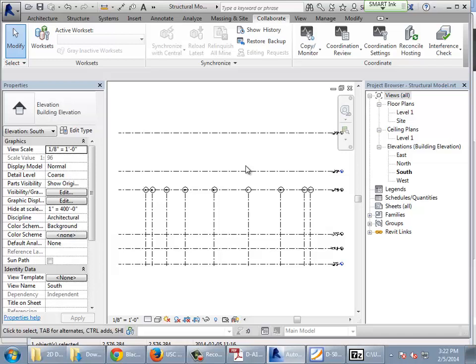But again, hopefully this won't happen to you too often. Strange, I wonder what you guys have done. Well, I saw the new level, so I just deleted the old one and matched. Ah, okay. So although it's matching, it's not really linked. If you copy monitored, it would work. I did copy monitor and I got that message, but I just didn't know what to do. I didn't know to go to coordination. No worries, we don't know either. We'll get that figured out.